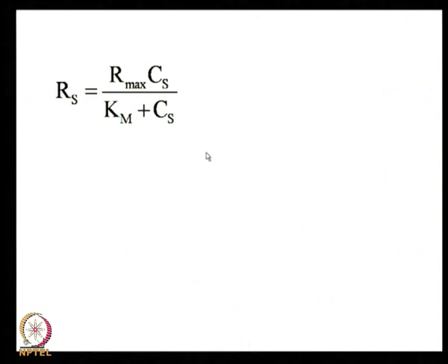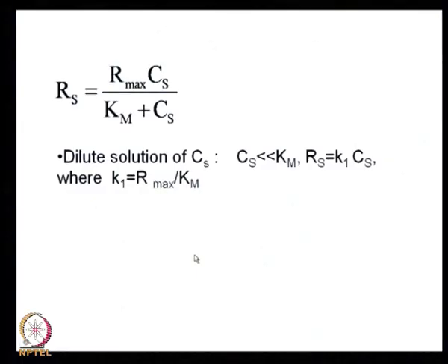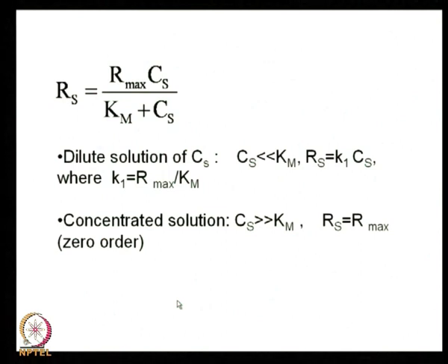So what we do is one of the things that we did before, which was to look at the two extreme ends of the problem, the two asymptotes: a very small value of Cs, where the system follows first order kinetics, and a very large value of Cs, where the system follows zeroth order kinetics. So what's the advantage? The real order of the system is a fractional order between 0 and 1, and if you can find the two bounds of the solution, your real solution is going to be bounded by these two solutions. If we can find the two bounds between the zeroth order and the first order, we are sort of in business.